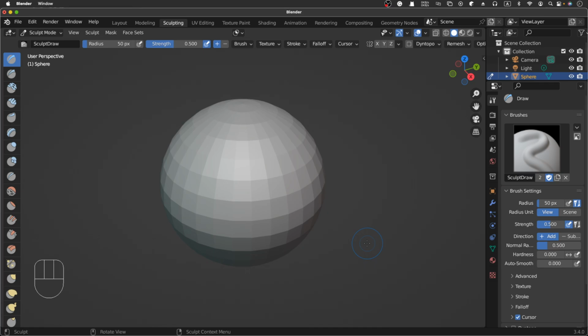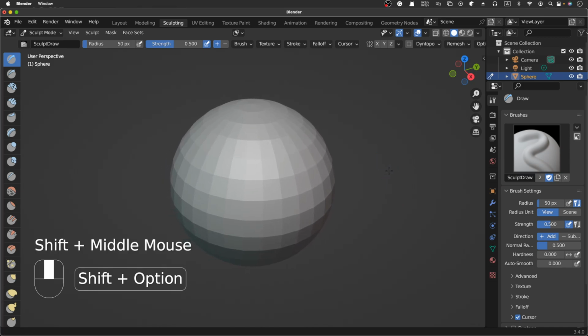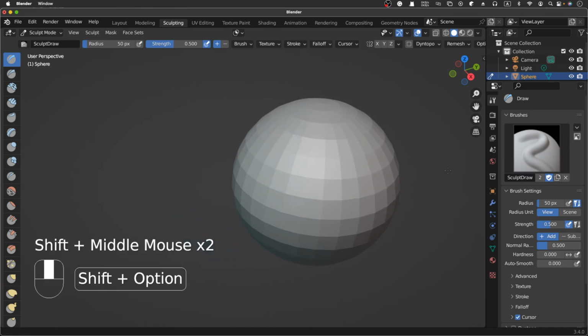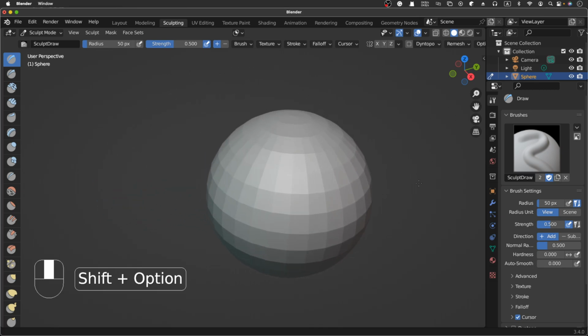So every time you want to hold the middle mouse button, you're just holding Alt or Option, right? And of course, you can hold Shift as well. Once you're holding Shift and you click, it's the left key, right? And if you're holding Shift and Alt, and you click and drag, you are essentially doing the panning.